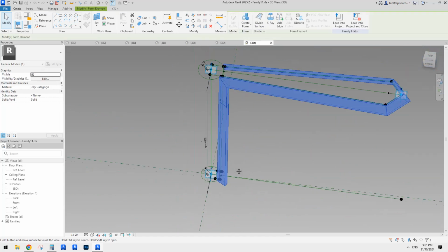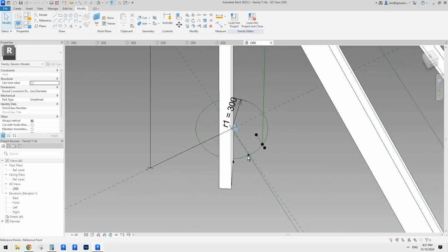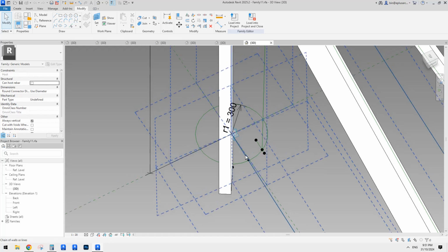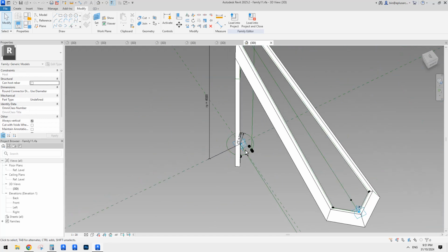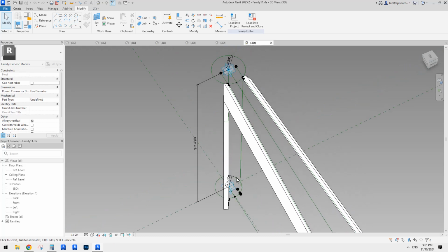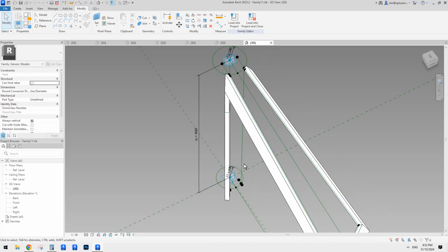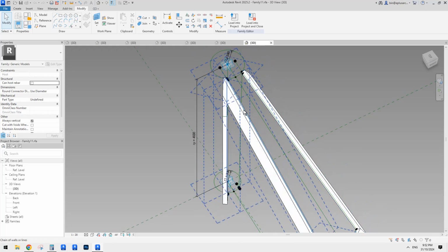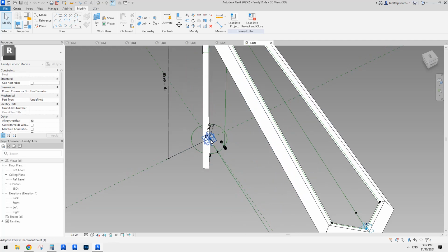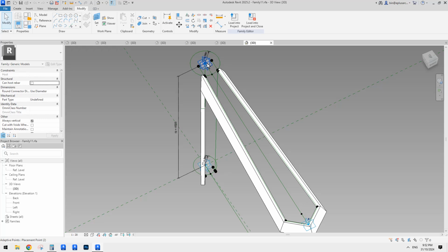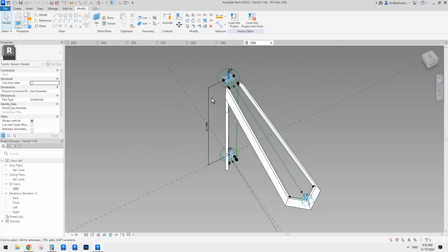And then there's a radius, which means we don't need to create that radius in that family. We can control radius 1 and radius 2 in this adaptive family. We just need to place it on the base middle point and the top middle point, and then with an offset. Okay, that's fine.